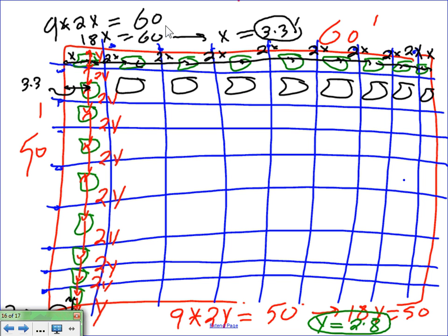Okay. The second thing is ground fault protection for equipment, GFPE. Please pay attention to GFPE. This protection is required on any system 1000 amps or higher, where the voltage is 480/277. What does it do though? It protects you from ground faults, not three-phase, not phase-to-phase, ground faults. Any phase to ground, it will protect you. So it's called GFPE. It protects you from a ground fault. So remember that one.